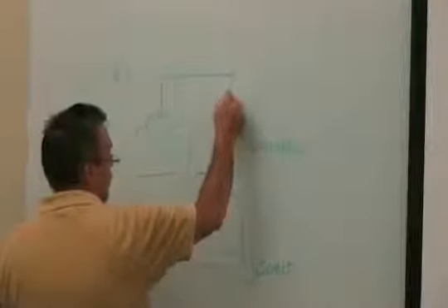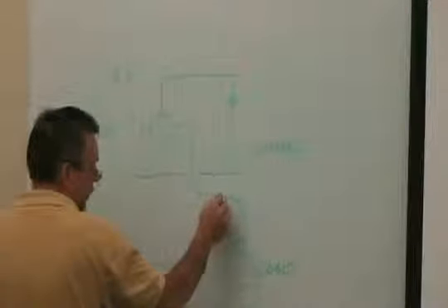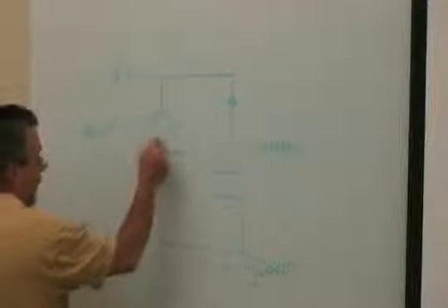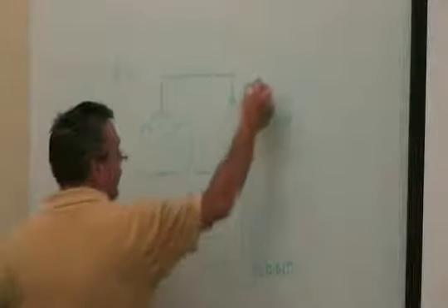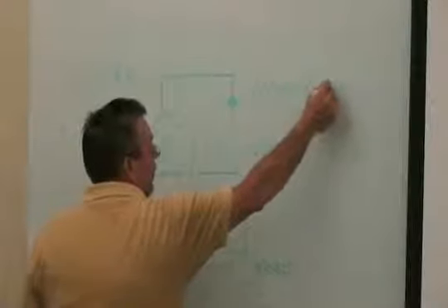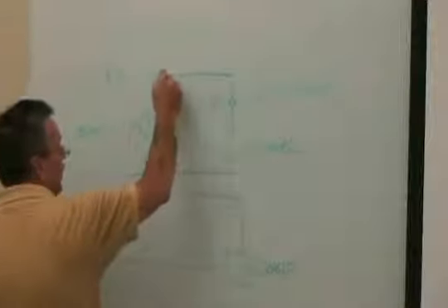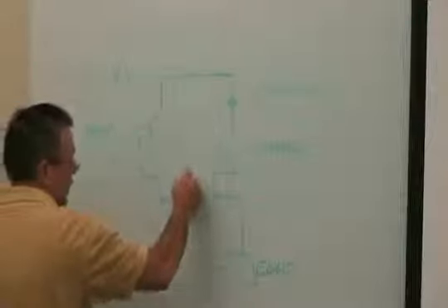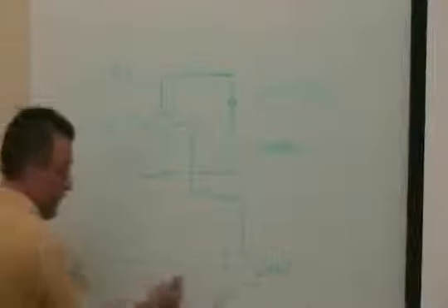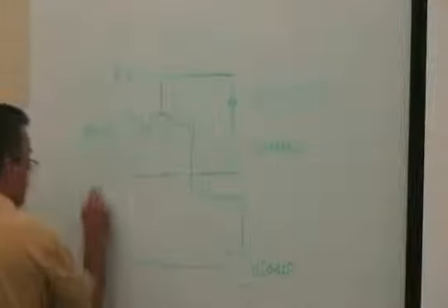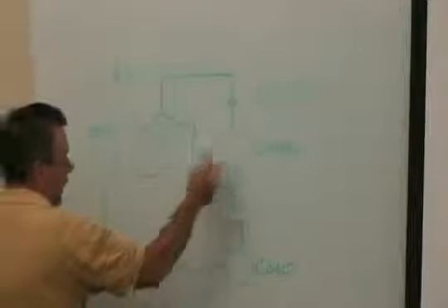So the compressor's pumping this direction, going through the reversing valve. It's going to send refrigerant to the condenser, into the evaporator, and then back to the compressor in cooling mode. Okay? So your refrigerant flow is here, hot gas, into the reversing valve, into the condenser, which is a water-cooled refrigerant condenser, into here, through some type of distributor, back to the reversing valve, back to the compressor.